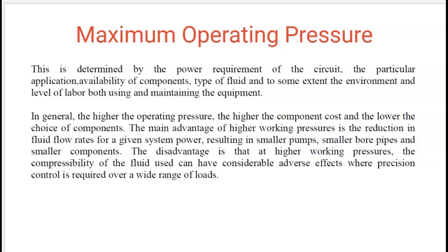Now, why would we select a pump with a high maximum operating pressure? What's the advantage of that? The main advantage of higher working pressure is a reduction in the fluid flow rate for a given system power, because it will have higher efficiency, resulting in smaller pumps, smaller bore diameters, and smaller components.